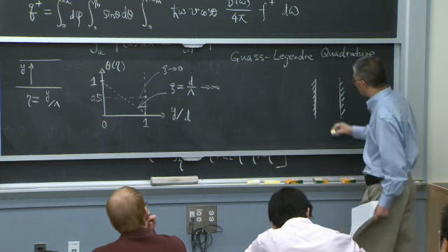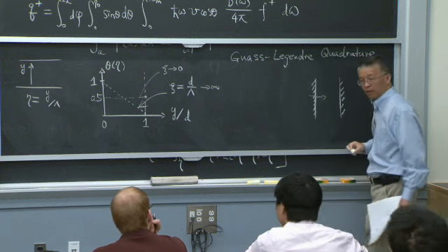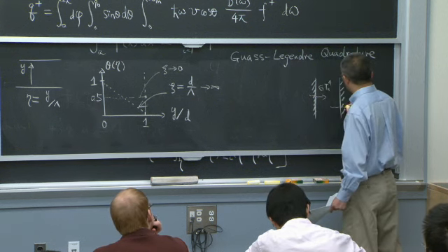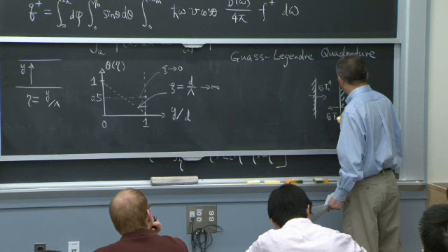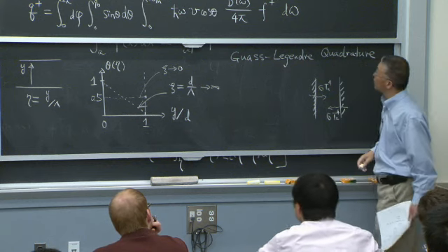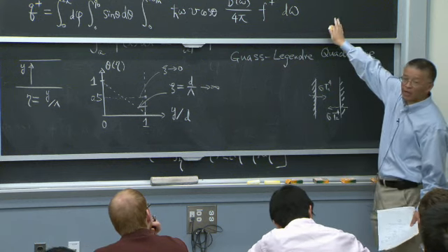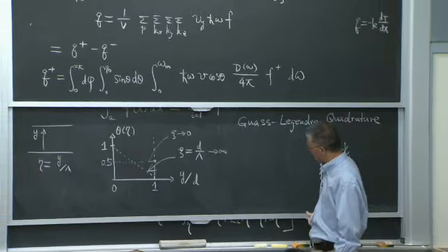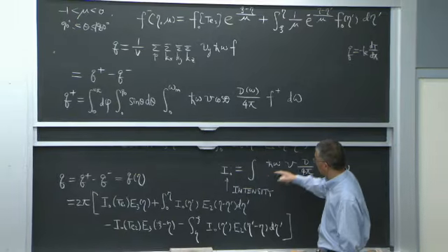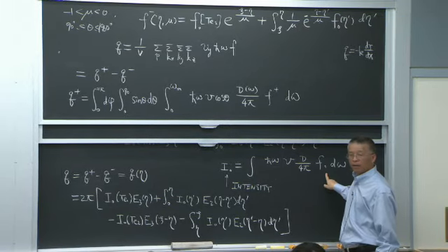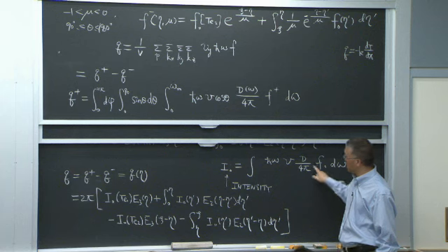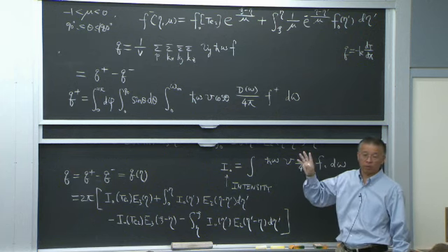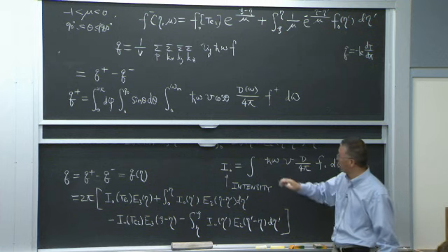When there's no internal scattering, recall we said that here is sigma T1 to the fourth power, here is sigma T2 to the fourth power. That's what you will get if you do I0 integration. Recall we did the I0. If you do the black body radiation integration from 0 to infinity, you get sigma T to the fourth power. That's the Stefan-Boltzmann law. Okay?